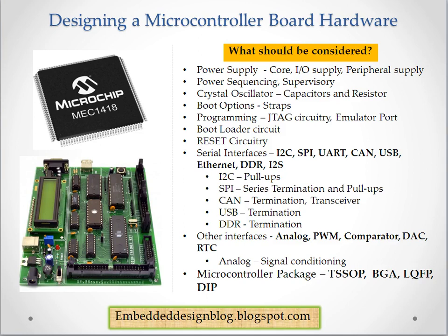Talking further, when a microcontroller is used, you will have a number of peripheral interfaces, here the serial interfaces. Assume I want to connect a memory like an EEPROM, which has I2C or SPI. So there will be I2C, SPI, UART. UART, as I talked about, can be used to load a program or for a simple serial application. And then CAN, which everyone knows is hot in the automotive industry.